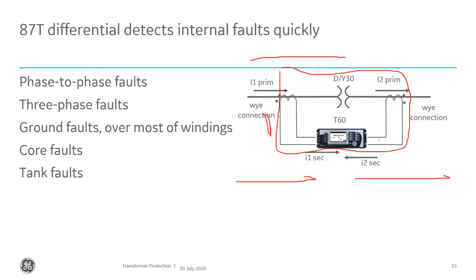And then that looks like 1 per unit at 180 degrees out of the relay there. Those two vectorially sum to 0. 1 at 0, 1 at 180, they vectorially sum to 0. Now, if I actually have a fault here, one of two things happen.